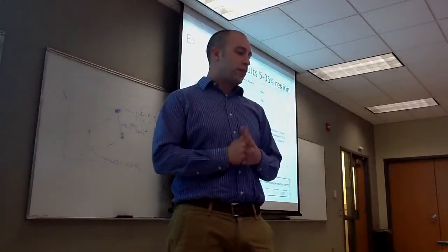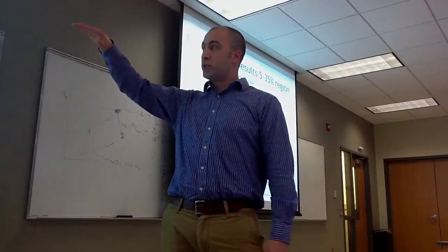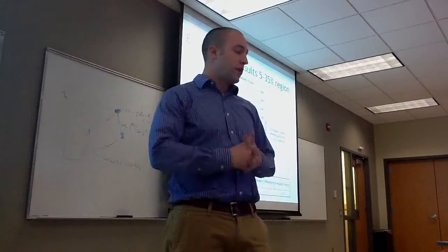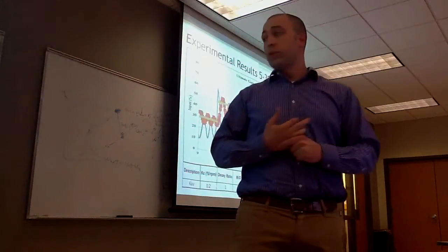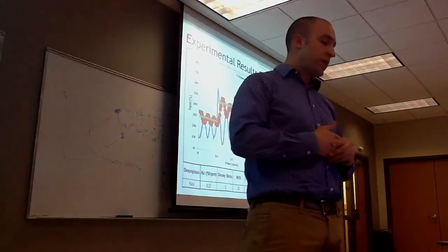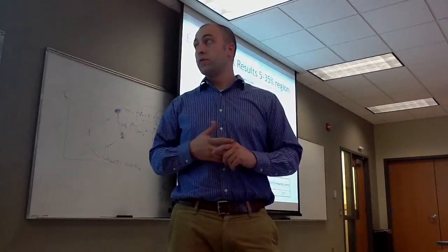Now here's the ultimate gain. It peaks out at first and then settles out, and it pretty much stays stable the rest of the way. So that's why I determined this to be the ultimate gain. The gain value is 0.2% per RPM, and has a frequency of 2.875 cycles per second.